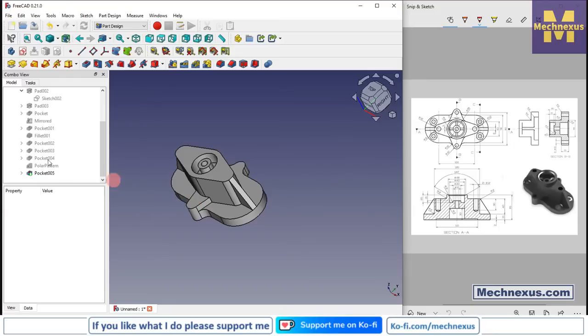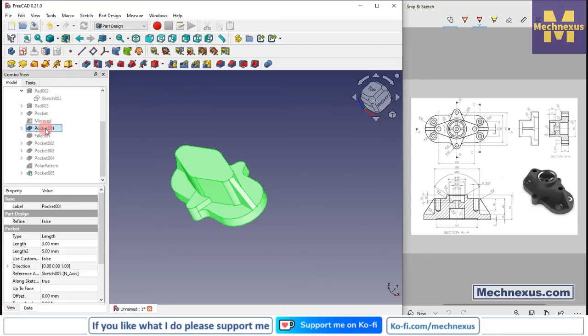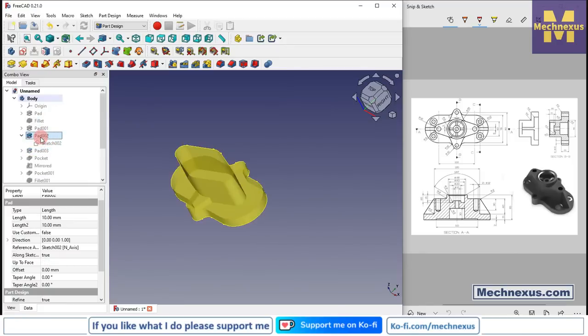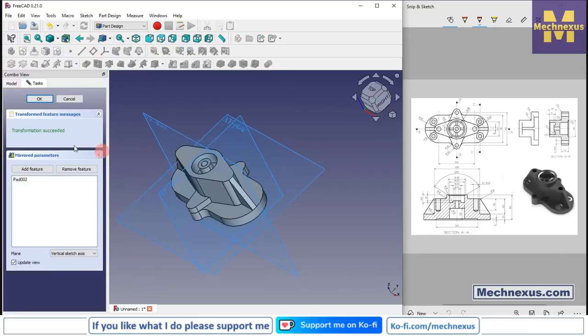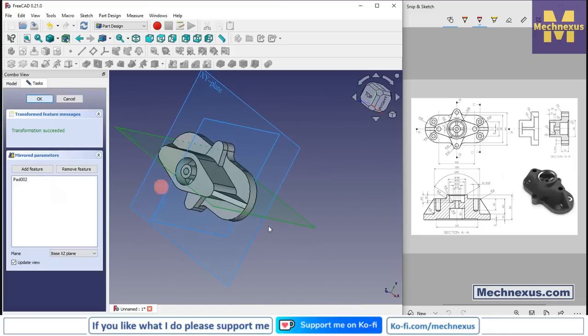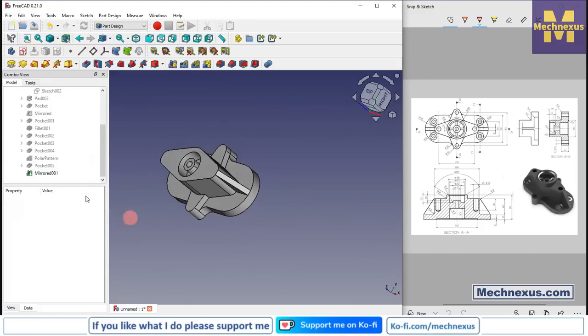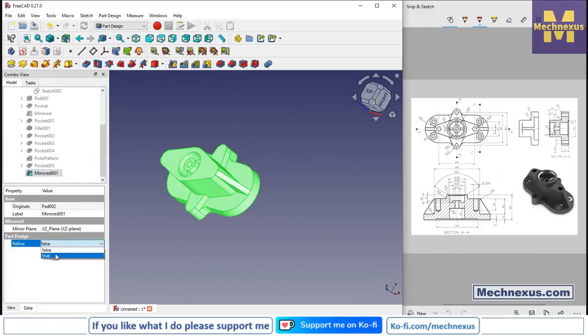So we will first identify the feature, which one is the feature. So this is the pad 002. If I go one step ahead, this is the pad 002. So we will select this pad 002, click on the mirror, and from here we will select reference and select this mid plane, click on OK, and we will select this mirror, refine is false, set it true,